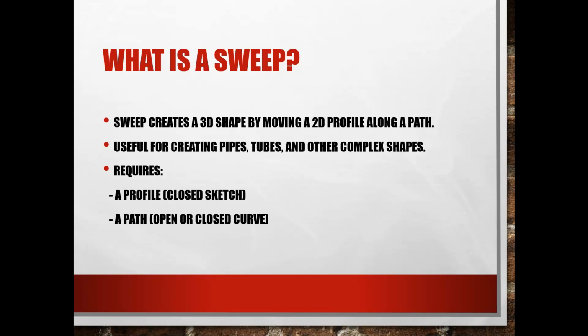Another thing that you're going to see is that you can make a complex shape, but you don't want them to self-intersect. You can make them self-intersect, like if you want to think about a donut or a ring or something of that nature, but those could be simpler to create using the revolve command. But you can create something that is a little complex. Typically with these sweeps, we don't have them self-intersecting.